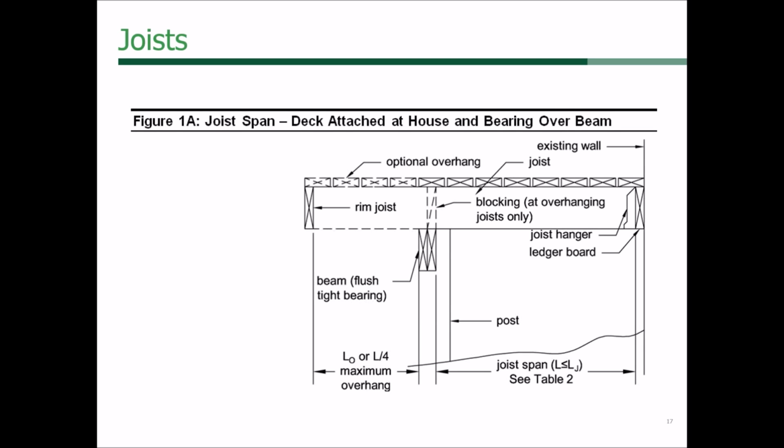If you're familiar with the National Design Specification for Wood Construction, or NDS, you'll know what the definition is usually like. Center point of bearing is center point of bearing, or something along those lines. But this is kind of an IRC world, so we made it a clear span. So it's inside face of support to inside face. That was to be consistent with our other span tables that are commonly used.